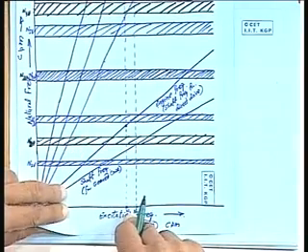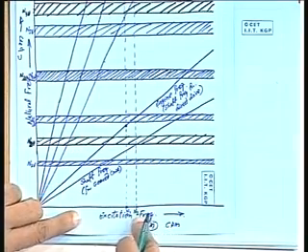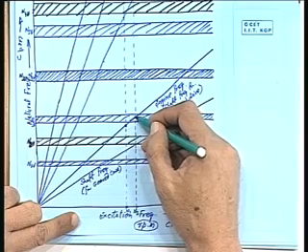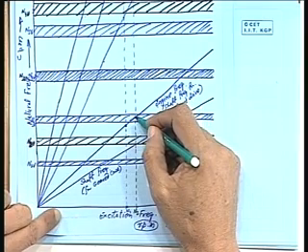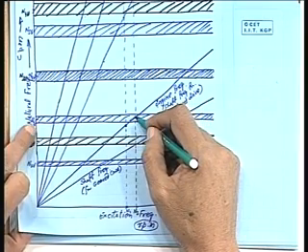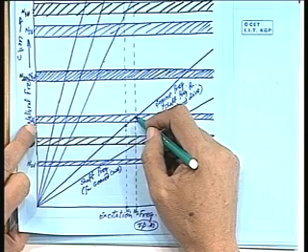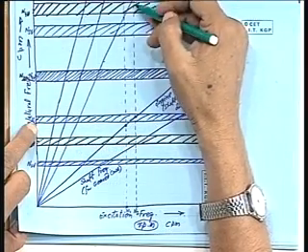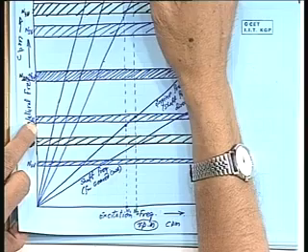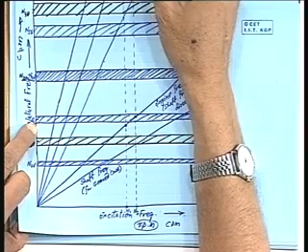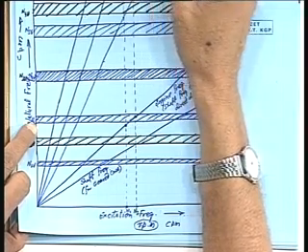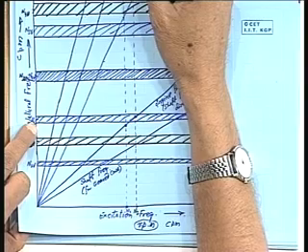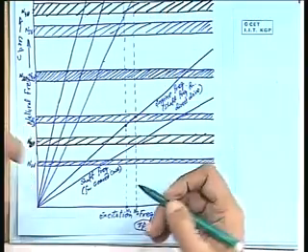Now this engine happens to be a very dangerous engine. You see, shaft RPM, engine RPM, everything is in one of the lowest mode RPM, vertical vibration of 3 node. It is going to excite that. And of course it is clear of 3-bladed, but 4-bladed it is just clear, if this band is closing here. Therefore this is absolutely not suitable.